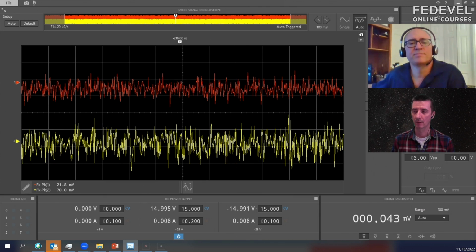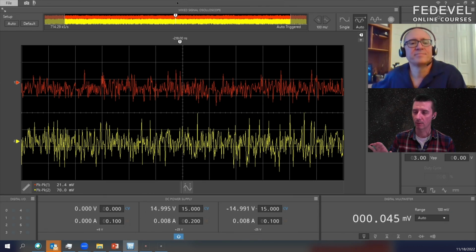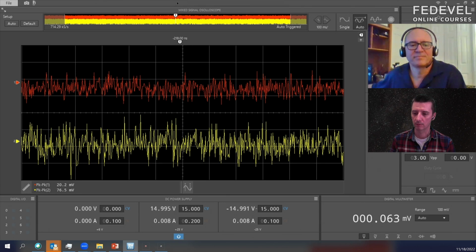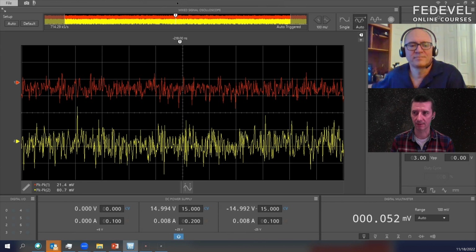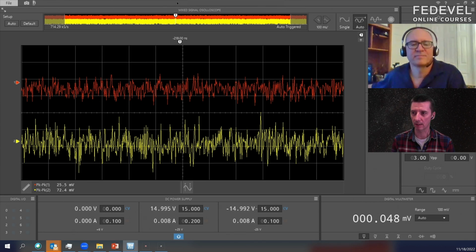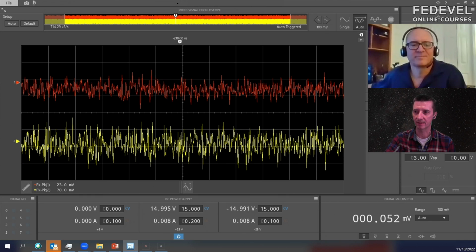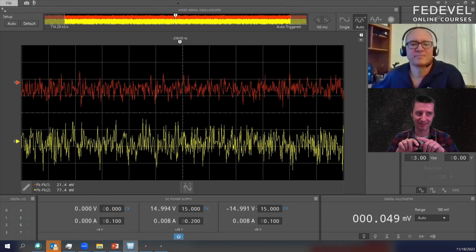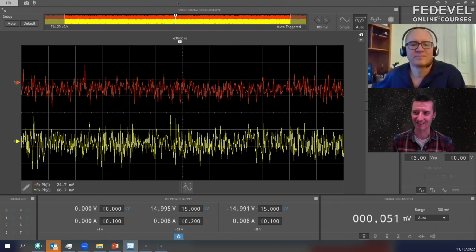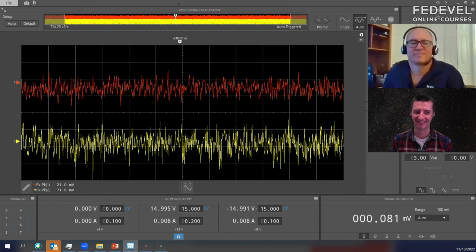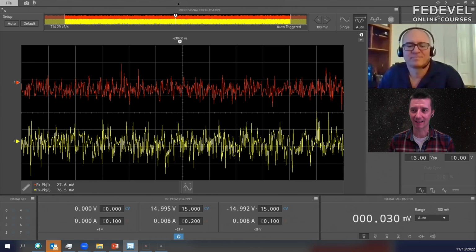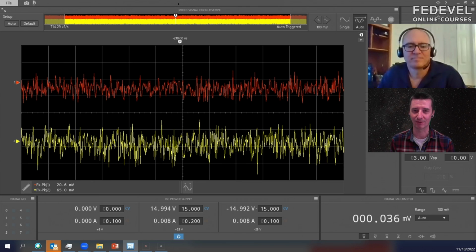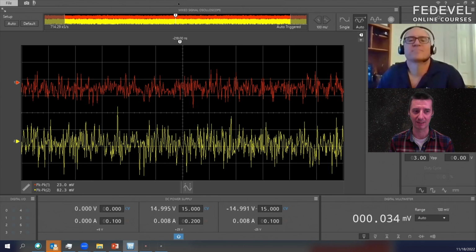Should I pull up the next demo? I'm just thinking, so I think this is like super good example to show how important this filter can be, because it can really clear up this signal, and that's basically the reason why in amplifiers there is this small capacitor across the resistor, because it's helping a lot. Yeah. So if someone needs like very clean amplifier, then they should simulate these kind of filters and use them in their circuit.